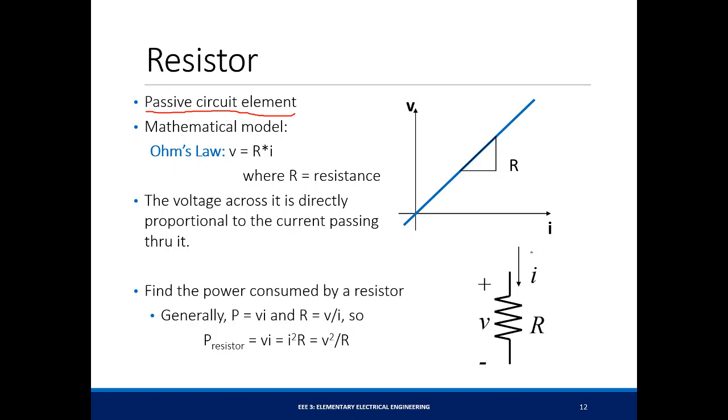Since current consists of positive charges, across a resistor, a voltage is developed from the flow of your positive charge to your negative charge. The voltage will always be, where the current enters, that's the positive, and where the current exits the resistor, that's your negative. So your voltage drop is always from here to here.